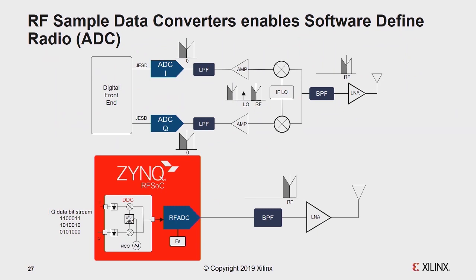That is not good for your 5G or A&D and test and measurement, because for 5G millimeter wave, you need up to 400 megahertz bandwidth. So that will limit your millimeter wave implementations with the JESD204B.